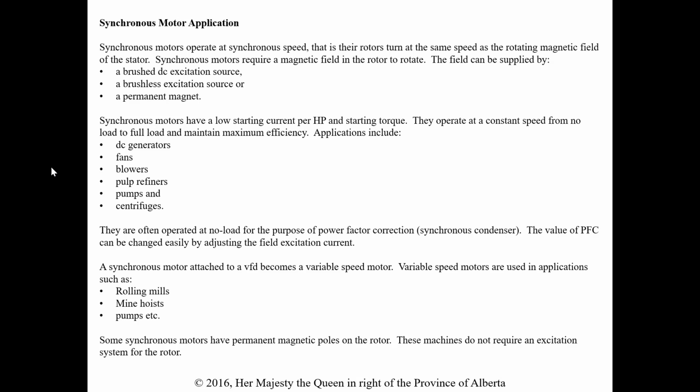Synchronous speed, for what we used in third, is the magnetic field that's going around in the stator. There's a magnetic field from the supply, and it's moving at 60 hertz because that's what we're going to hook to the armature windings in the stator. We hook our supply voltage there, so it creates a magnetic field in our three-phase motor that's rotating around within the stator. Even if there wasn't a rotor in there, we would still have that rotating magnetic field.